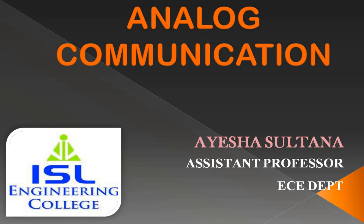Before going to pulse position modulation, we'll quickly revise pulse width modulation. What was the definition? It is the modulation technique in which the pulse width is changed or varied in accordance with the instantaneous value of the message signal. The carrier is a pulse train, and the width of the pulses is varied in accordance with the instantaneous values of the message signal. That is called pulse width modulation.